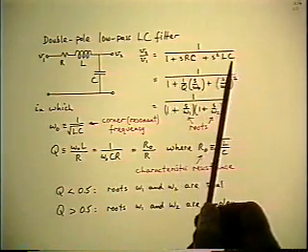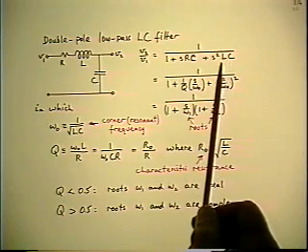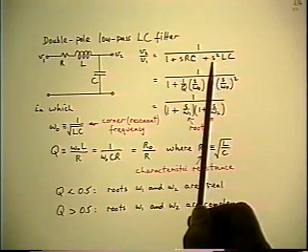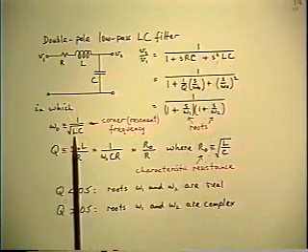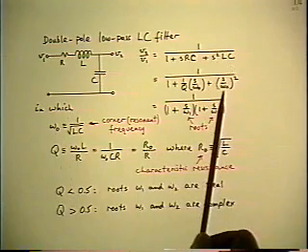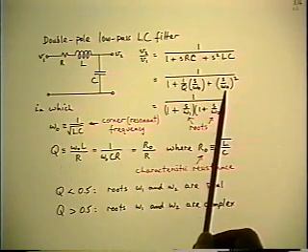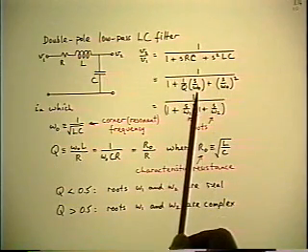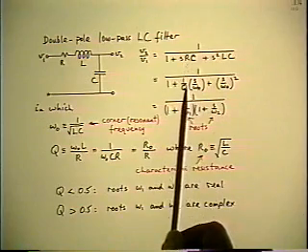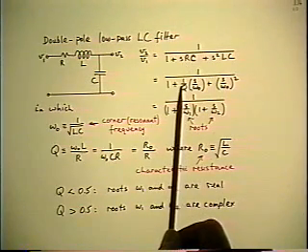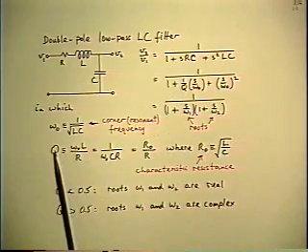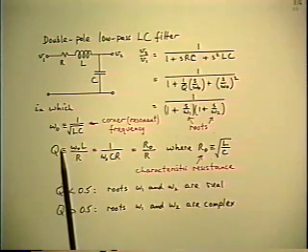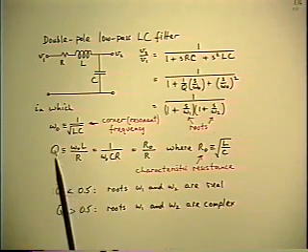The corner frequency is by extension of what we did with the single pole function. It's the coefficient of the highest power of S. So you define 1 over LC as being the square of the normalizing frequency omega 0. Then you put the middle term with the same normalization, and what's left behind in the coefficient of the middle term is dimensionless, and you call that 1 over Q. And having done it in that way, you find you can write the Q in various different combinations.